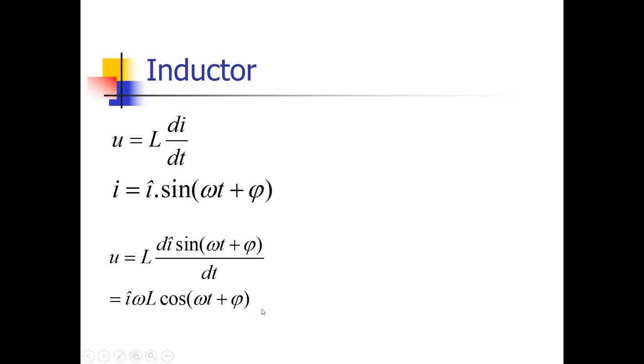Well, we can first of all draw a time domain plot in which again the black curve is the current and the green curve is the voltage. And we see that the voltage leads the current, and that is of course because the voltage is a cosine and the current is a sine, and the cosine has a top earlier than the sine, so the voltage leads the current. That is what we expect from an inductor, and that is what we see.